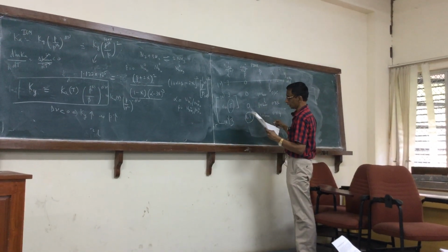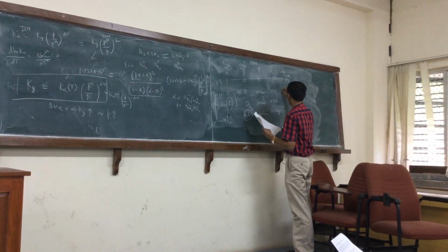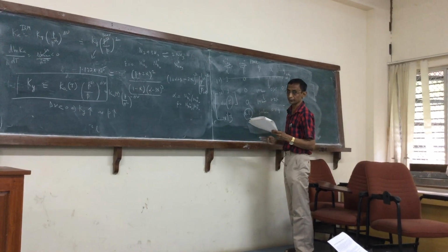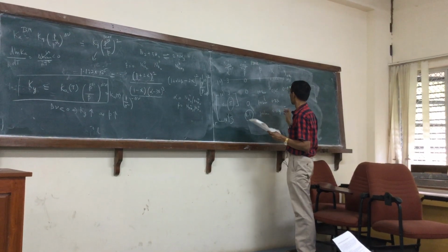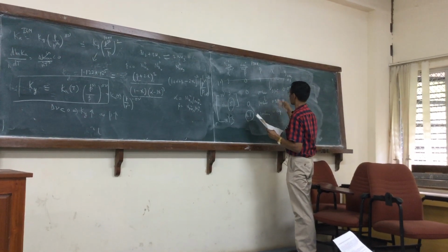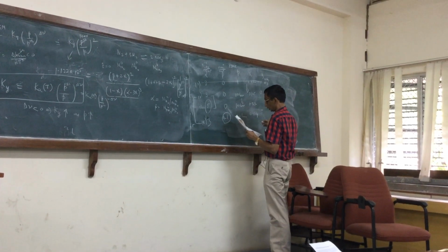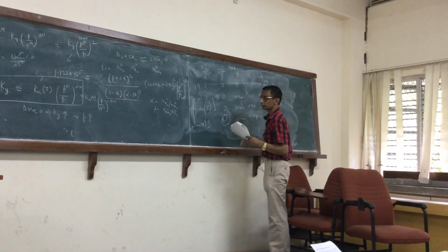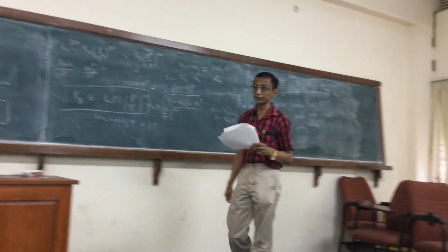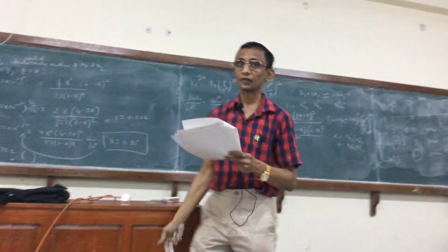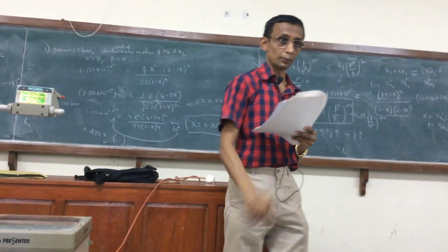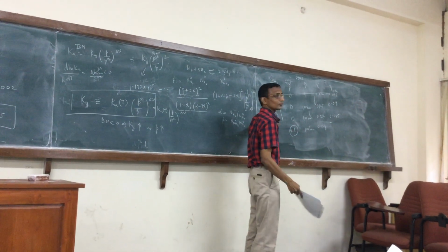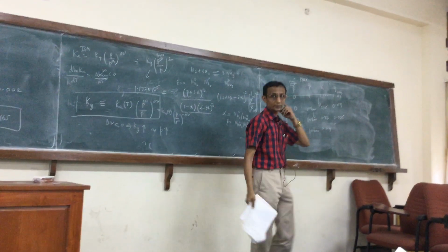And so this turns out to be 0.09, clearly a big improvement, but still not very high, because the conversion itself is quite low. And for here, even though the equilibrium conversion is quite greater, almost 1.5 times more, the number of moles of ammonia is smaller, obviously because of the huge amounts of hydrogen we are using.